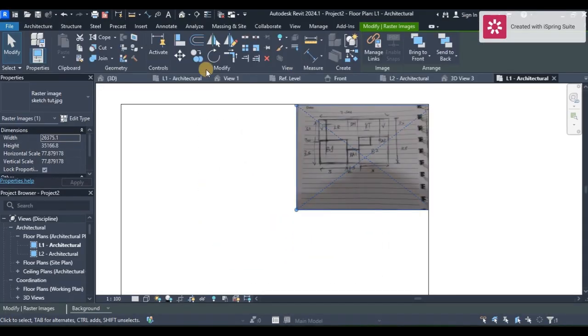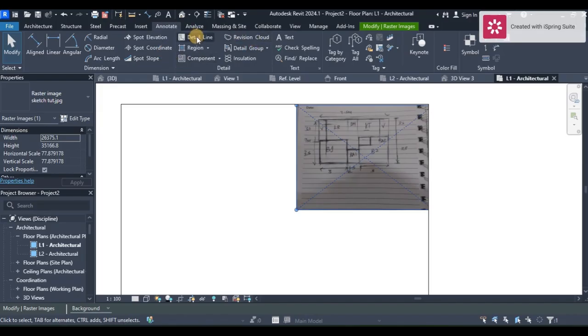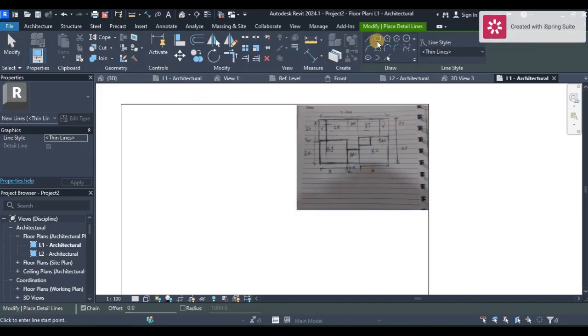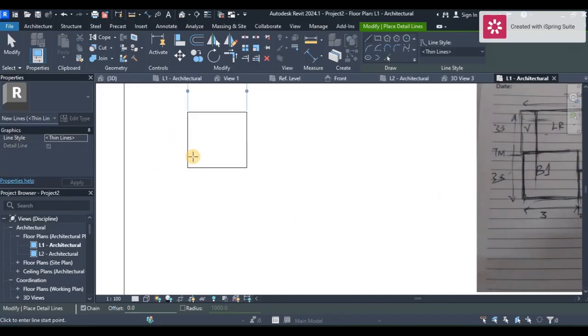First, we're going to start by drawing the lines to represent our plan, like we did for Archicad. So I'm going to go to annotate, and then to detail line, and I'm just going to sketch out my plan. I'm going to draw the first area, which is the length, 7500, then the width, which is going to be 7000, like it was, and then the length again, 7500, and then we finish the loop with the other side.